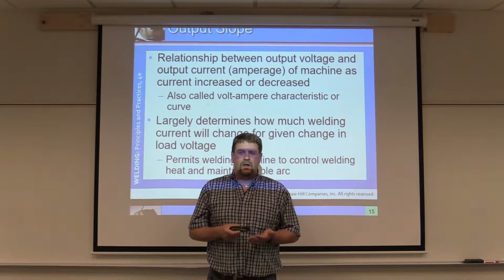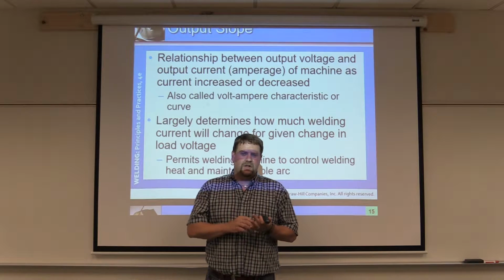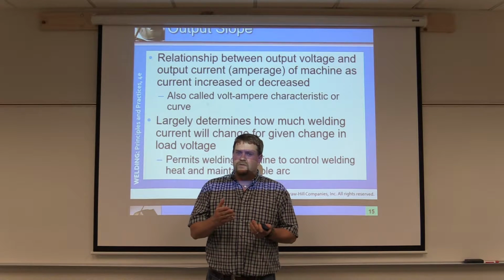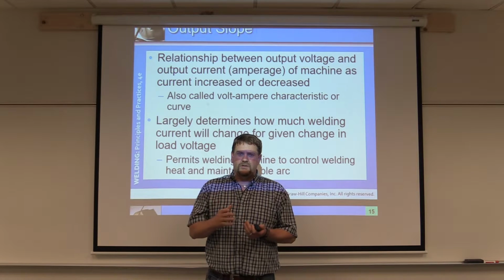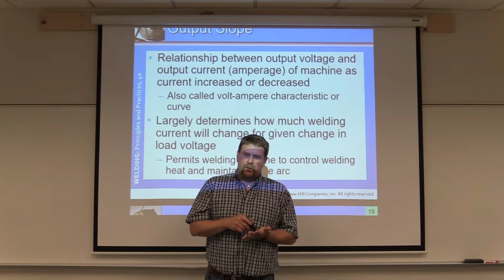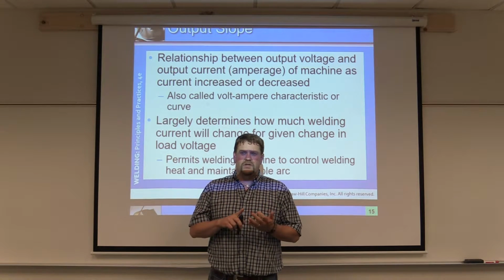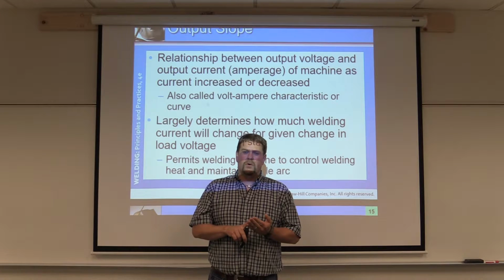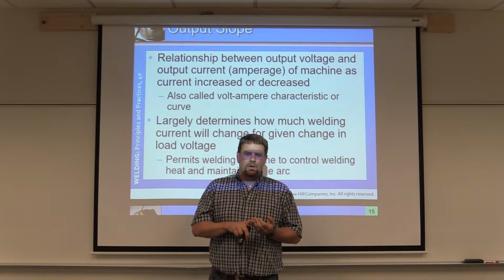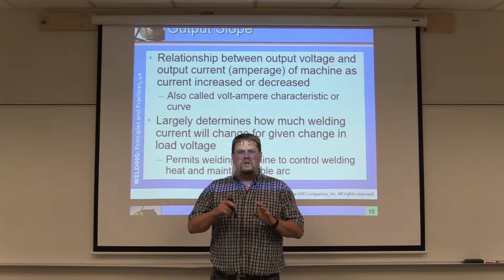It's a lot of heat already, but it cools off very rapidly as soon as we're done. Doesn't mean that the entire piece stays 9,000 degrees forever. Depends on thickness and so forth. But the more amps that we put into it creates more heat, also creates more distortion, creates discontinuity, grain boundaries, and a lot of other things that we're going to get into later on.